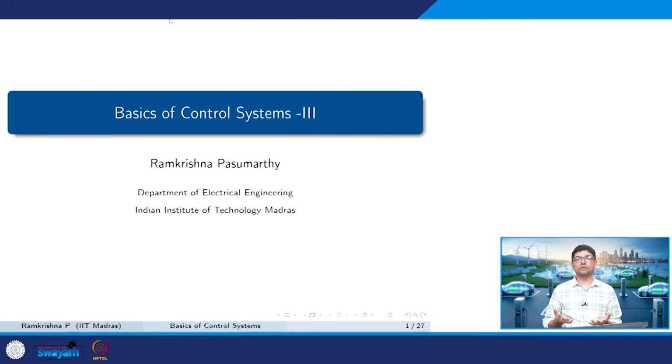We just did analysis on first and second order systems. We looked at how systems can behave when they are of underdamped nature, overdamped nature, critically damped, undamped, and so on. We also looked at how systems can be made faster and slower by looking at the time constants in the first order case, or the zeta and the omega n in the second order systems, where we could control the peak overshoot, the settling time, and so on. And always it was a trade-off between faster response and overshoots.